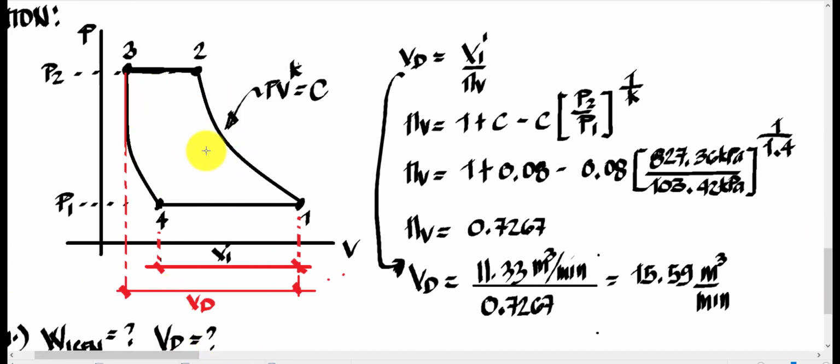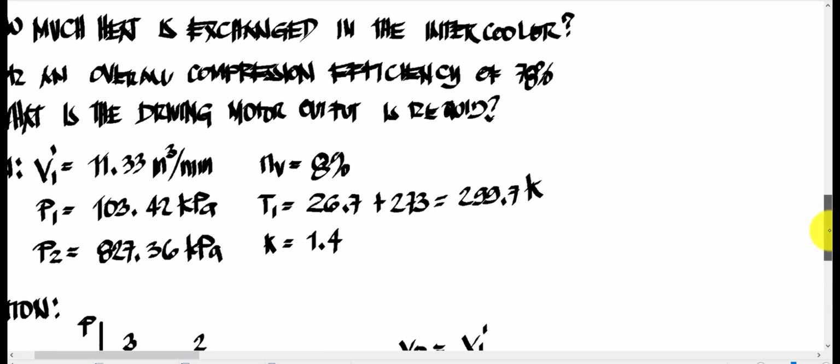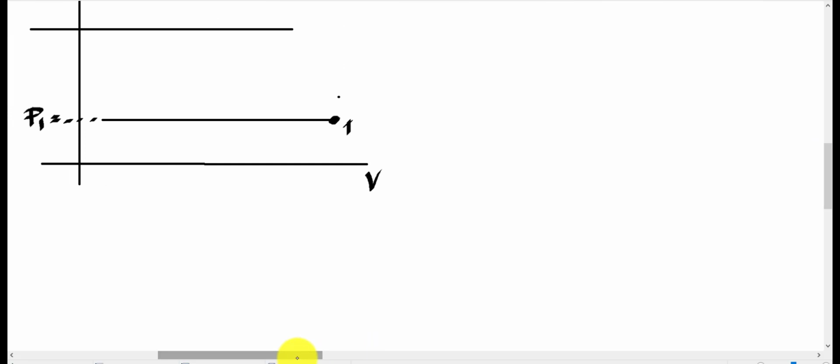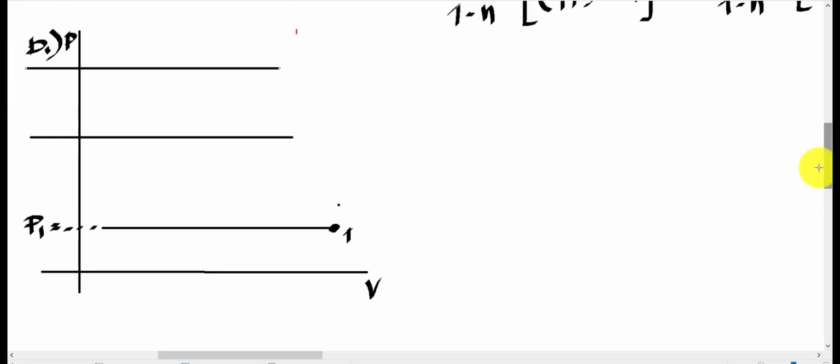So we try to slice the PV diagram we had before. Usually we have the whole area, no? So you notice here the work, there's only one compression. Now we're going to do a multi-stage. Then I'm going to slice, since we're going to divide the work from here, since the first stage and second stage must have the same work, equal in work.